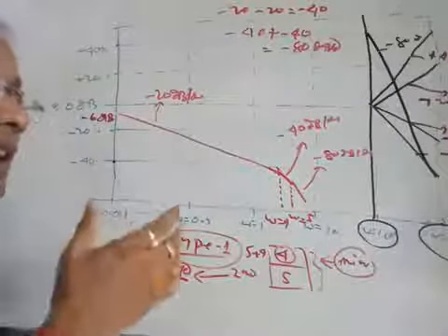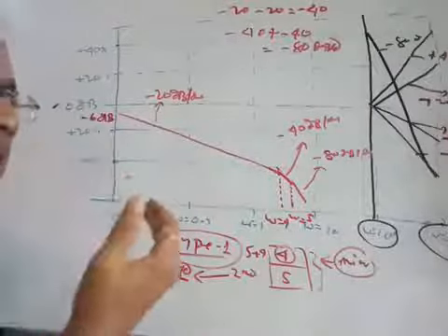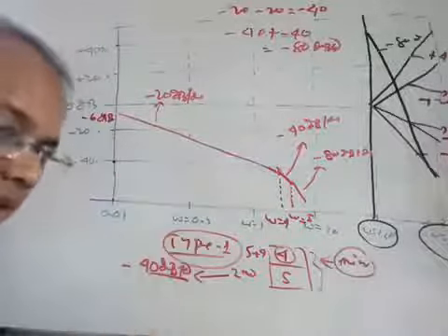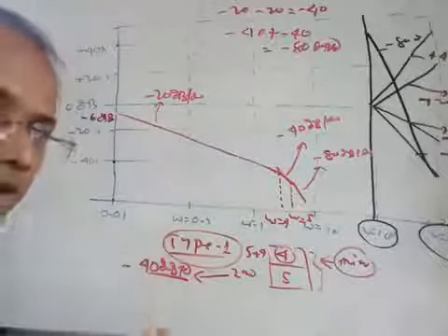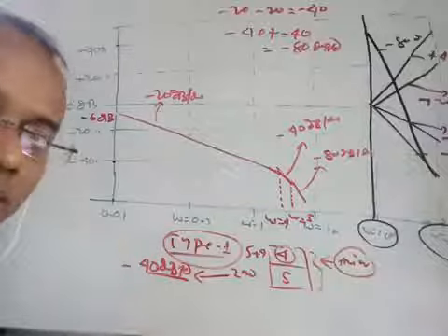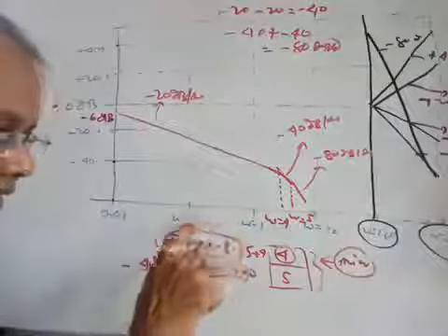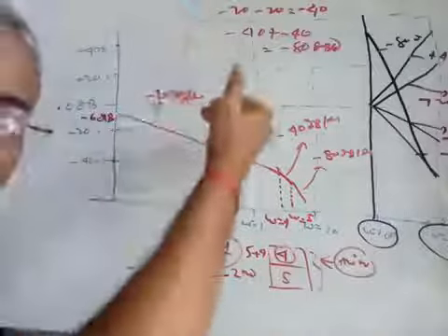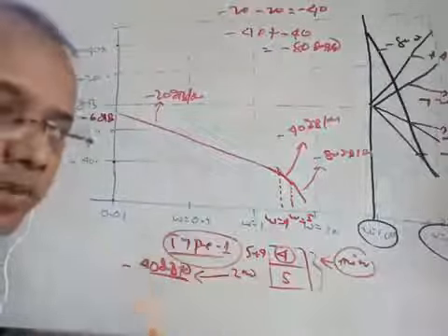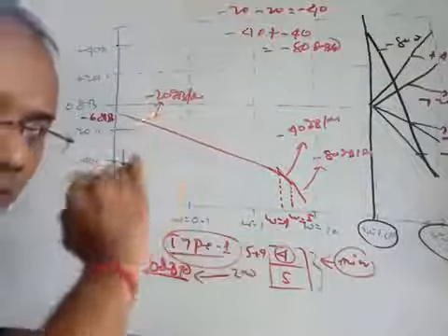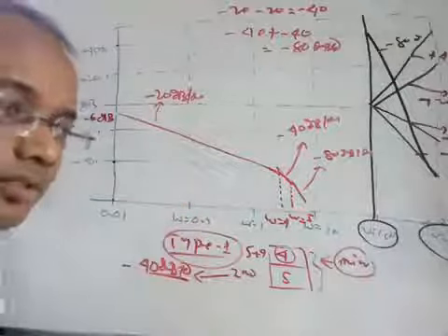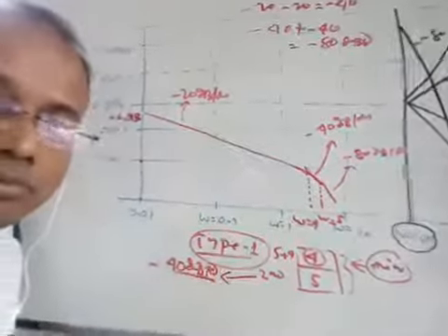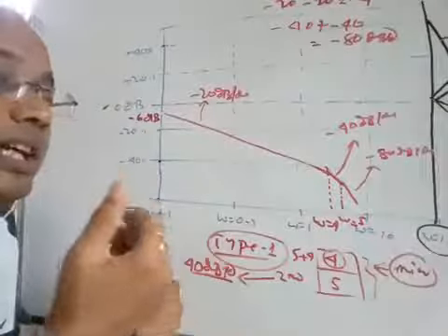And you see, in the next class we will discuss the drawing of the Bode phase plot, because in order to get the stability, or in order to complete the Bode diagram, you need a single graph where, corresponding to the frequency axis, you have the Bode magnitude plot on the top of the graph, and next a Bode phase plot at the bottom of the graph, such that for any variation of the frequency, we get the variation of the phase as well as the variation of the magnitude, and from that stability can be analyzed, right?